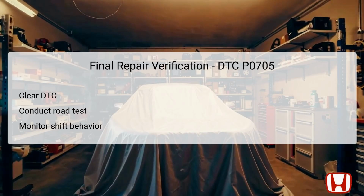Following this, a thorough road test should be conducted to evaluate the vehicle's performance closely. During the test, the technician should monitor any shifting behavior and ensure that the shift position indicator functions correctly, without blinking or inconsistently lighting up. This verification is essential to confirm that the repair has resolved the initial concerns and that the vehicle is now operating correctly. If during the test any codes reappear or unusual shifting persists, additional investigation may be required to ensure that all issues have been accurately addressed and resolved.